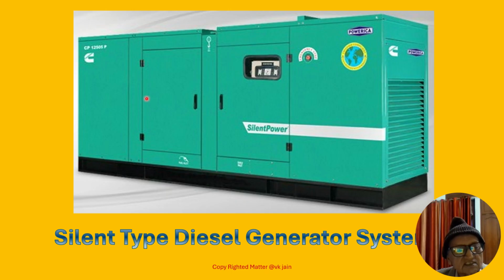This canopy looks like a cubicle system, and this is provided with silent type diesel generating set system, which in all the cases above 750 kVA, that is from 800 kVA onward, must be canopy based as per CPCB.